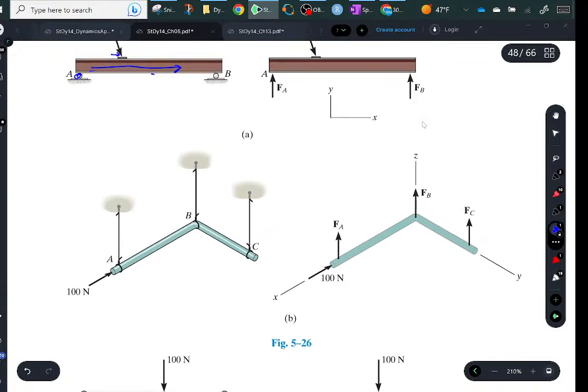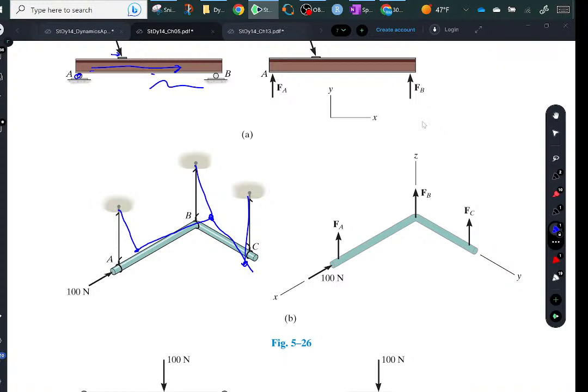Now this one, okay. So this one may seem improper, and from a static viewpoint, it is. But this one's not as bad as the ones above, because what will happen is this member will move off and probably change its orientation so that it'll force itself into a position in which equilibrium can be satisfied.